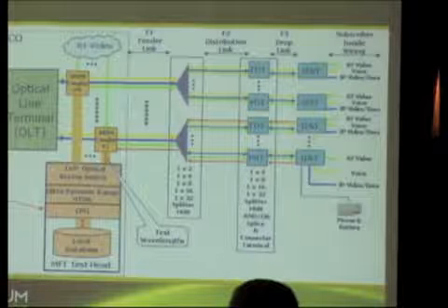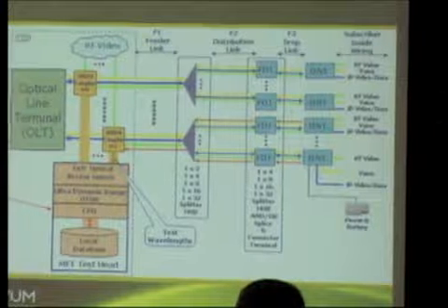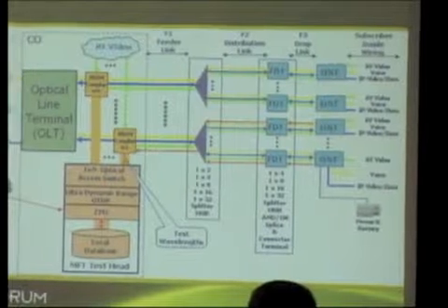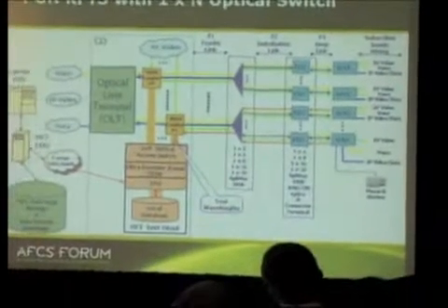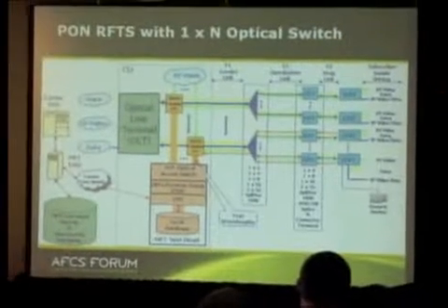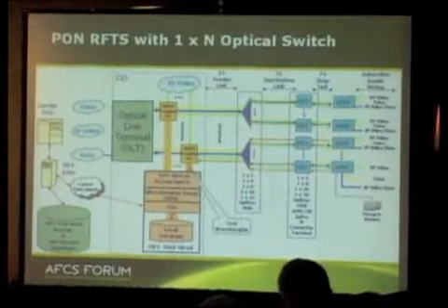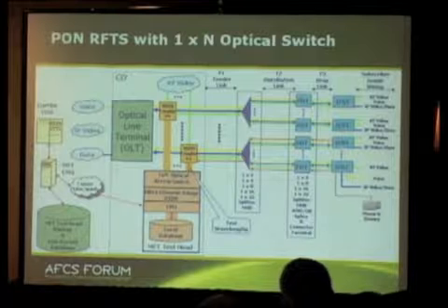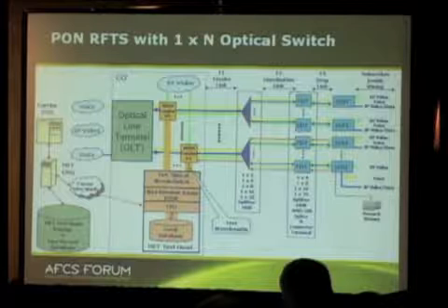And we shoot the fiber, and then we can detect which fiber branch on the F2 side is in trouble. That's the uniqueness of this type of system. The issue isn't saying, I've got a fault in the F2, but I don't know which one of 64 or one of 32 fibers. The real issue is, can you tell me which fiber is broken and where?